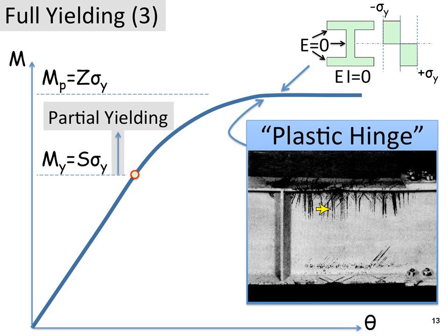The other thing I'd like to say is that my diagram is a tad out of scale. If you take the ratio of the plastic section modulus to the elastic section modulus, some folks tend to call this the shape factor, it's really only about 1.15, at best maybe 1.2 for the type of wide flange shapes that we might use in design. So that means that this point is really about 5/6 of the way along to this moment here. But just so you folks could see it, I sort of separated them a bit. Now the picture is different in minor axis bending, but we're not going to be going there tonight.